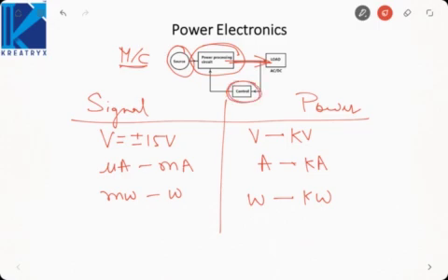So what this control circuit does is, it measures the load parameters and then it controls the switching of the power processing circuit. What is meant by switching of the power processing circuit is that this power processing circuit is made of different types of switches. So this control circuit will control the state of different switches, which switch will be on and which switch will be off, based on the parameters at the load side.